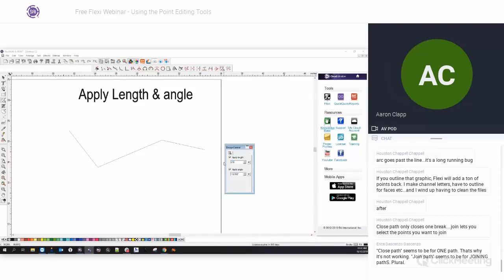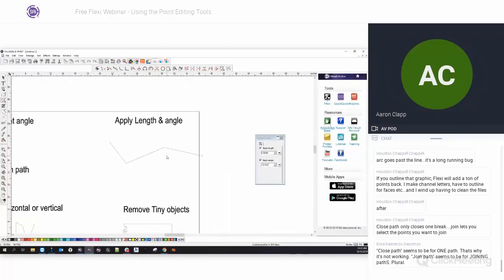So if I want that to be 2.5 inches, click on that line and it'll make it shorter. It'll also make it longer if I change it back, so 6.5. And now that line is at 6.5 inches. I can do that with any one of these lines by holding control and clicking on those lines. It gives me that information. You can also turn one of them off if you don't want it to do the information for both, so that you can restrict it that way.